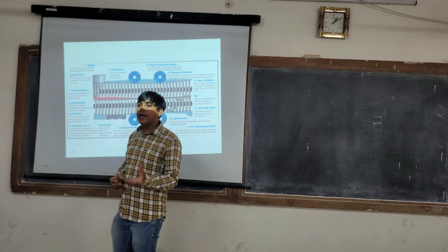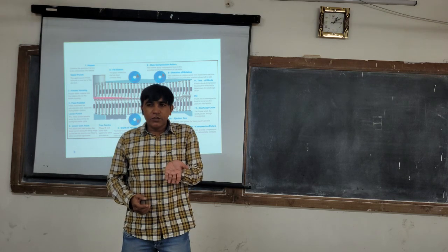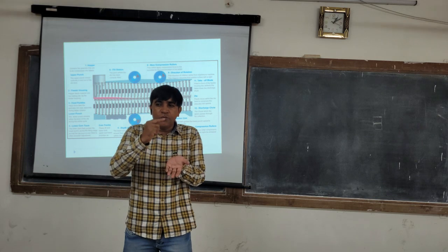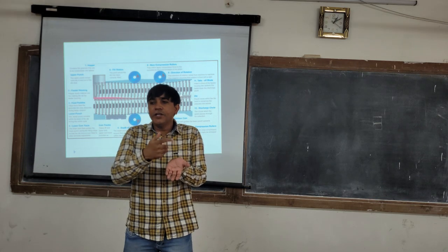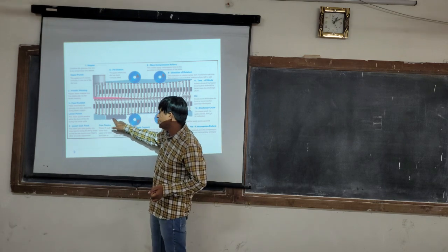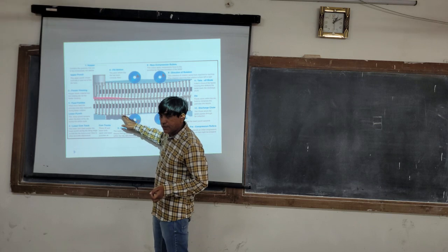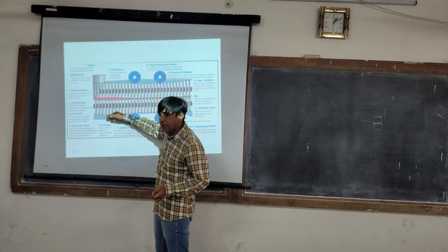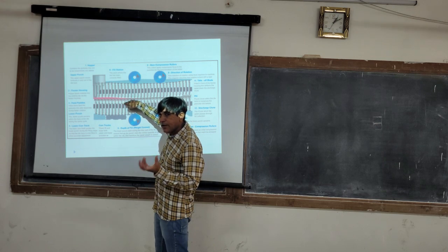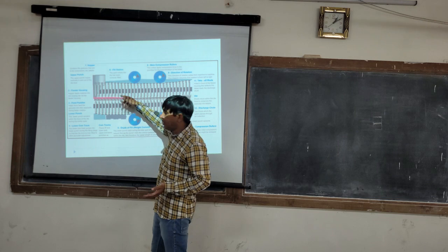Normally, initially the die is overfilled, and then the ramp is somewhat tilted so that the extra mass will move upward. This will help in rearrangement and proper die filling, and that is why the arrangement is done like that. So this ramp is used for weight adjustment. We can tilt it, we can increase the angle. Initially the die is overfilled, then this punch rises, which will push the mass upward and rearrange the granules, and then there will be a scraper which will scrape the granules.